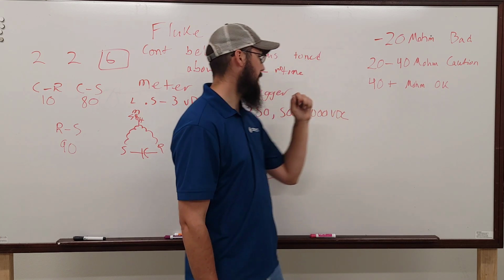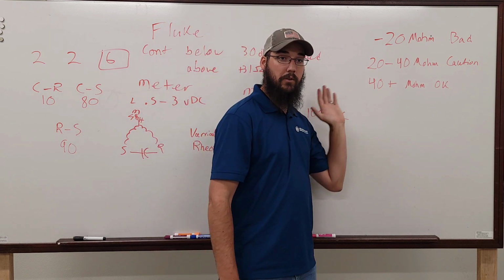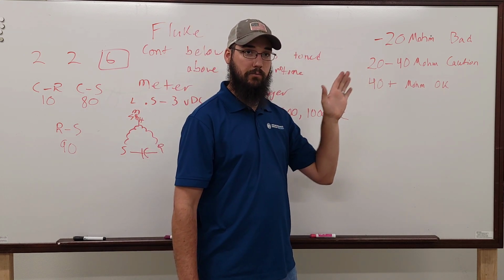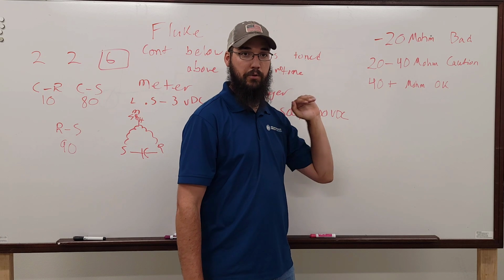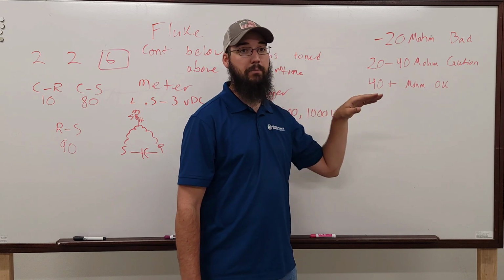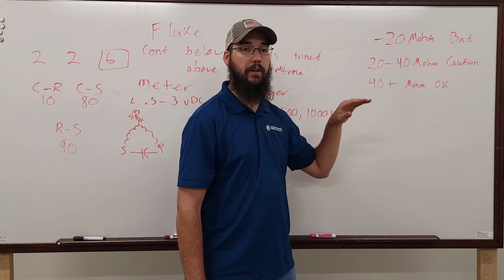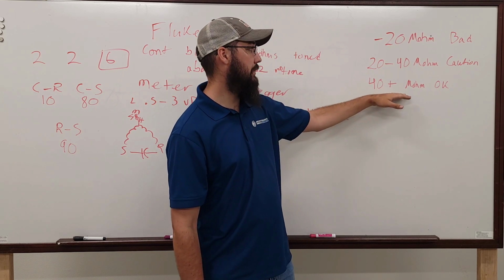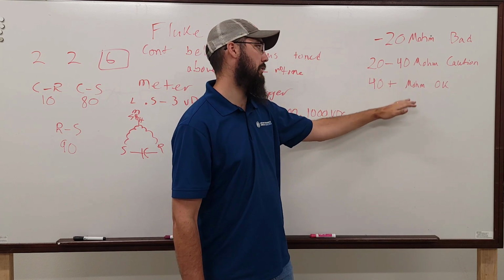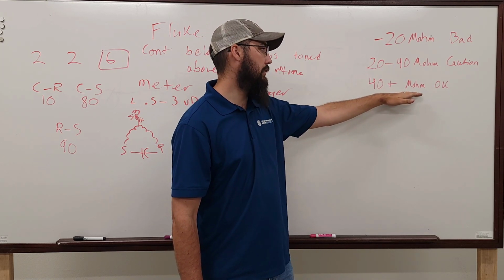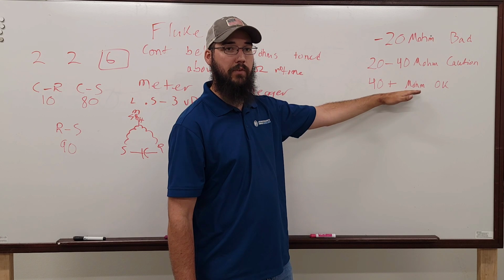Because that drive, again, well, not up there anymore, the pulse width modulation has very different characteristics than a pure sine wave. So that drive picks that leakage to ground up, and it isn't going to play that game. And you can use these, nobody pays for it, but you can use these to do long-term failure prediction.